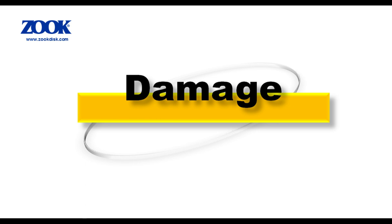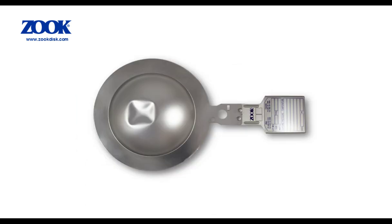Rupture disks are engineered products, but they can be delicate and fragile. Especially with reverse-acting disks, any minor damage to the disk dome will negatively affect performance and cause the disk to burst or collapse low. All disk manufacturers will take extreme care to fabricate, package, and ship you their disks, but handling in the field is just as critical. Disks should always be handled by their edges or tags, never touch the disk dome. A disk showing signs of damage should not be installed.